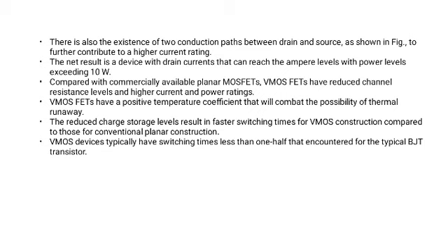Comparatively, commercially available VMOS FETs have reduced channel resistance compared with other planar MOSFETs, and they have higher current and power ratings. VMOS FETs have a high positive temperature coefficient, so they have a low possibility of thermal runaway, and they also have reduced charge, giving much faster switching times.